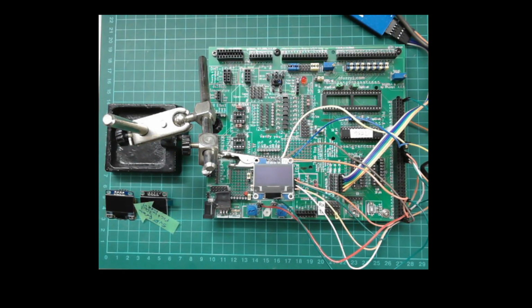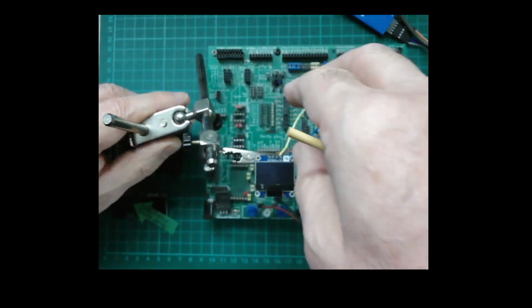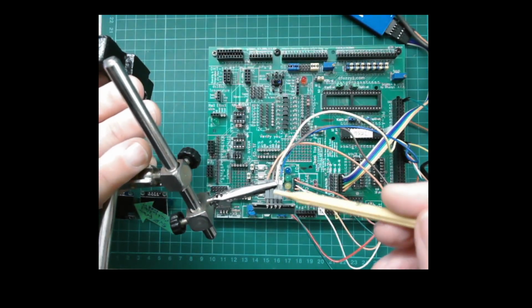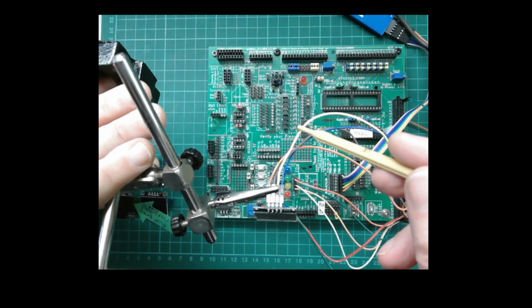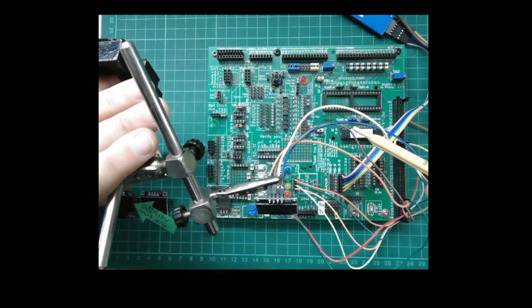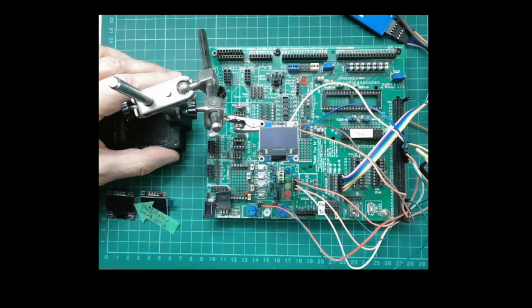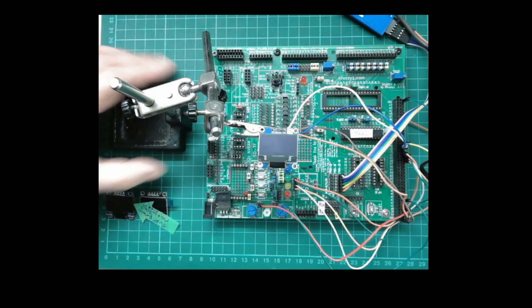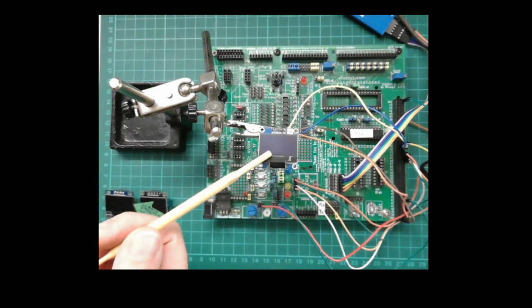I'll put those down. What have I got? I've got a chip connected here. I've got 4 leads into the back of this device here. Let me just rotate it slightly. Oh, I can do it like that. Here we have 5 volts. I've got the ground. Yellow is always my clock line. Blue is always my data line. And they are hooked up into the ports I'm going to be using, C4 and C5. So that's the last time you'll see that, because our job is to discover what device this is.